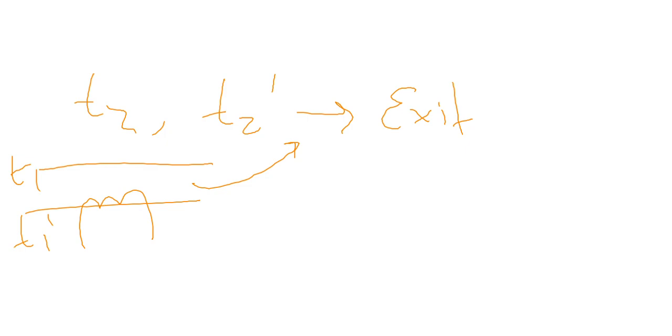The second part of the problem is getting the bypass factor. So bypass factor is what? As we had said, it is the ratio of the temperature drop with bypass to the drop which we achieve without bypass. I'll just draw the diagram again so that you understand what bypass factor is.